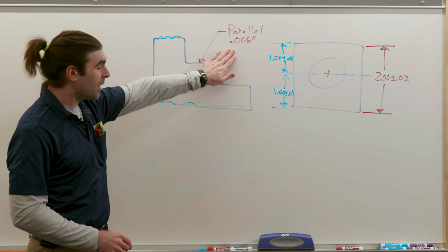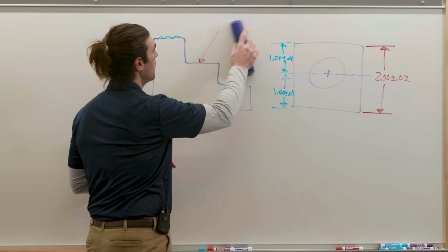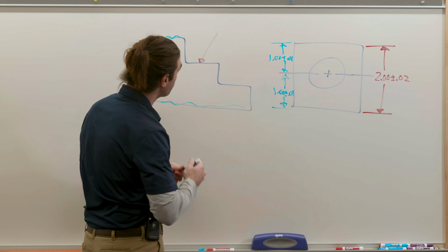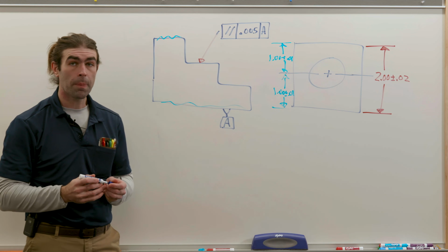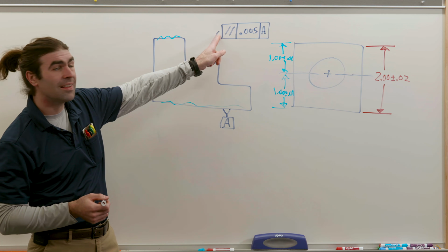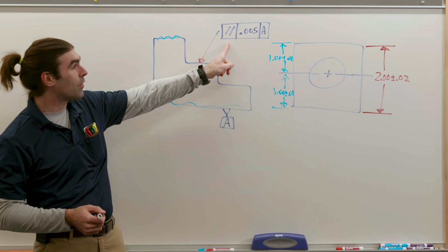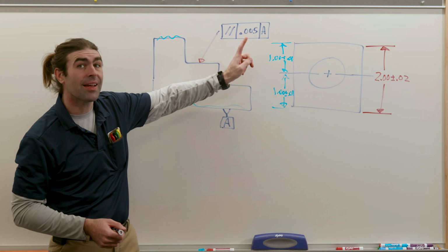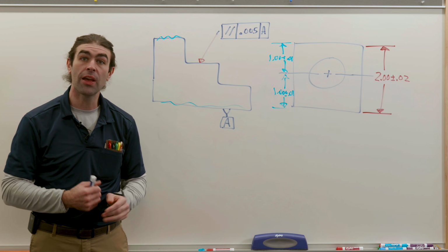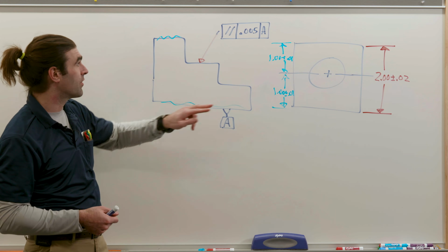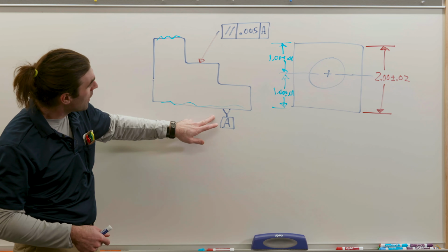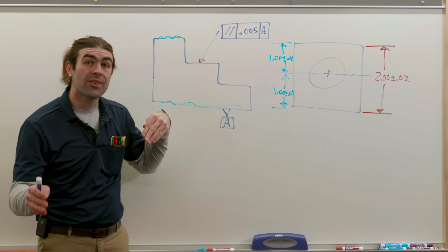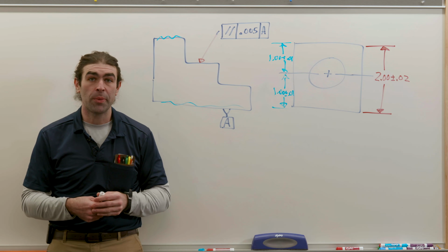So to make this into a proper GD&T callout, we're going to use the feature control frame. A feature control frame is a box. In this case, it's leader directed. The very first box will have the geometric characteristic symbol. The next one will have the tolerance. After the tolerance will be the datums. In this case, with this particular tolerance, we only need one datum. We're going to write our datum feature symbol down here and connect it to the bottom surface. So now it's explicit what the drawing requirements are.